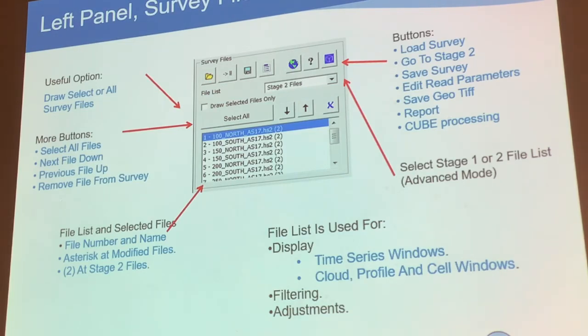Then you will see the multi-beam files. So earlier, remember I was saying if you put the automatic to stage 2, you will directly go into the multi-beam file. But if you don't put automatic, you will go to stage 1 first. And then it will just show you the navigation lines first. Stage 1 is about selecting the filters, and when you press the second button next to the yellow button, it goes to stage 2 and you will see the images.